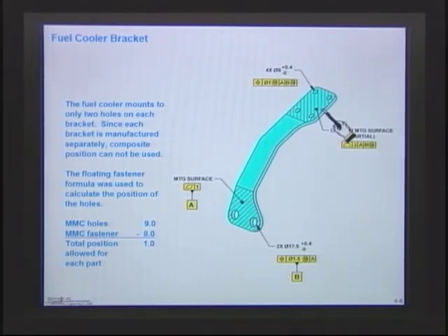So remember with geometric tolerancing, the difference is you point to the feature and you tell me that feature better be there within so much, and that's what we're doing. See? The symbol goes right to that surface.